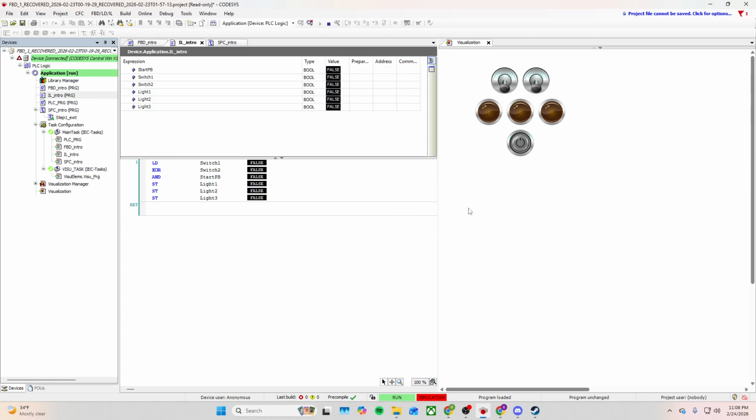First, I will verify that the start push button truly acts as a master control or control power. By flipping the switches, you can see that they do change from true to false, but the lights do not activate. Even if the XOR logic becomes true, the AND operation with the start push button should force the final result to stay false. This does confirm that the start PB locks the outputs.